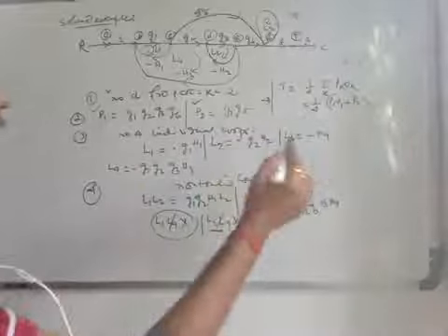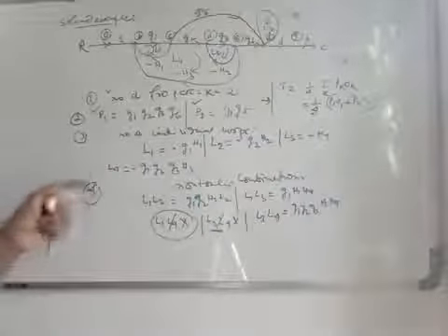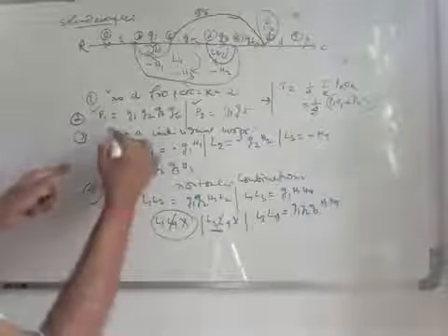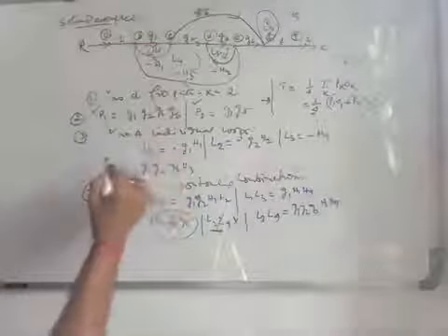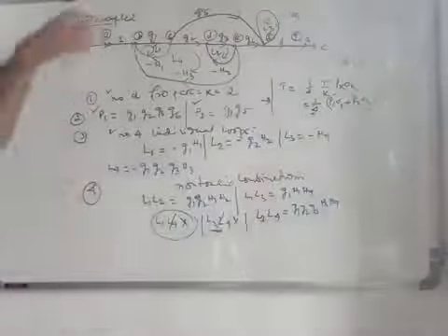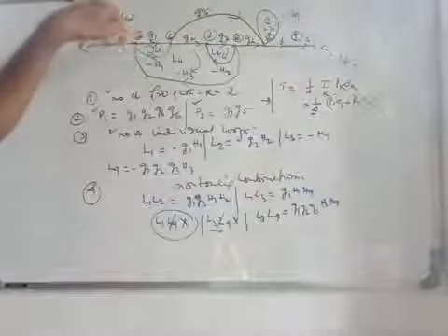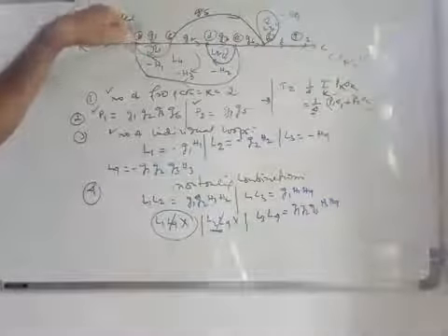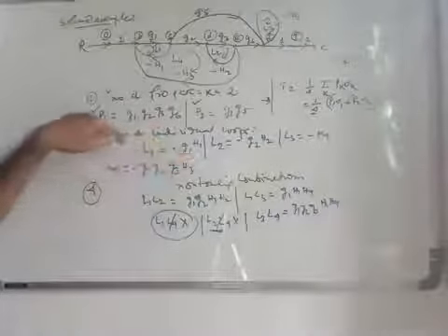Next, to find out the delta, delta is a function of basically loop gains. So in that case, you have to find out the number of individual loops. You see there are the loops. I have already written them in other colors to mark them. So L1, L2, L3, L4, there are 4 individual loops with loop gains. Loop gain means the product of the branches used to construct the loop. This is G1 into minus H1, so minus G1 H1 is the loop gain like this.